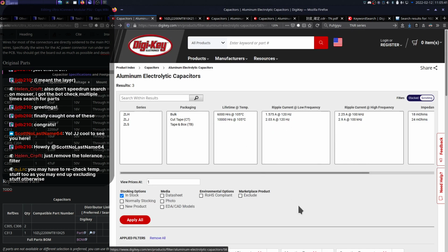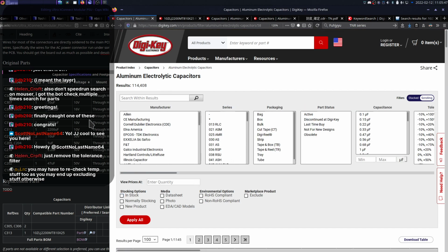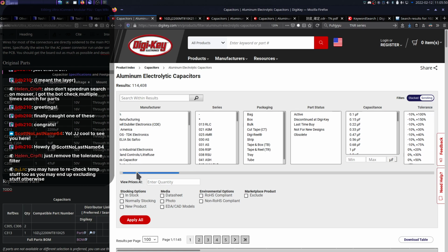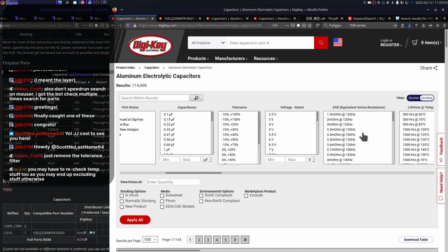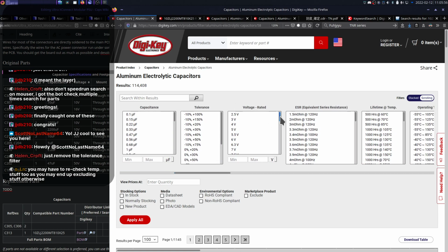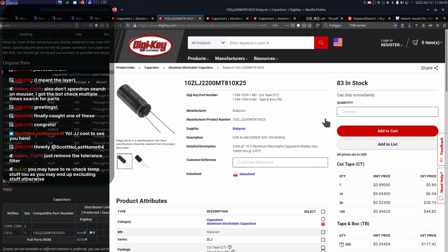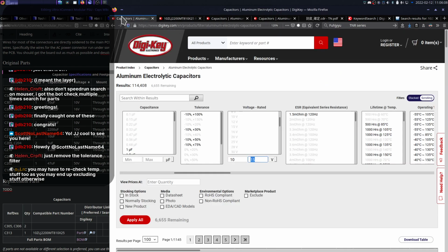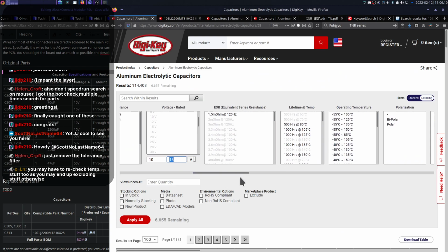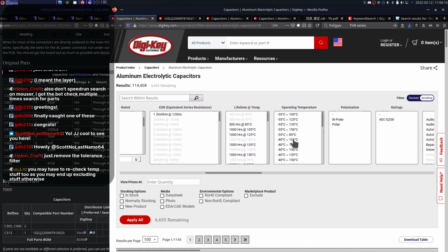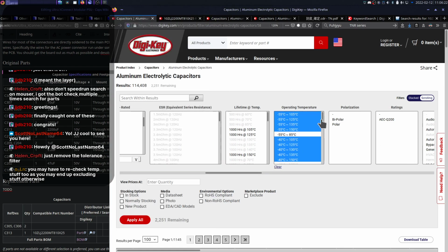All right. Let's just start from scratch. Aluminum electrolytics. All right, starting from scratch here. Okay. Voltage, 10. Oh, wait, no, I can do, let's go 10, 15. You know what? I didn't pay attention to what the voltage rating was on that. What was that? It was 10. I like that, lower's better. Okay, ESR, I'm going to get what I get on that. It's got to be at least 85, or at least 105, I mean. Let's just pick those.